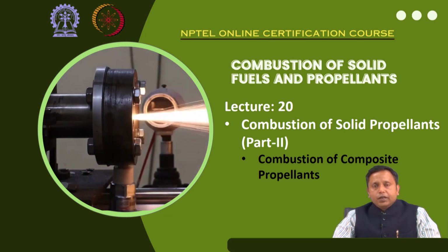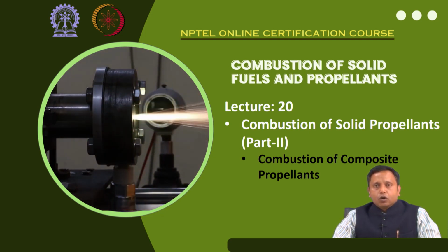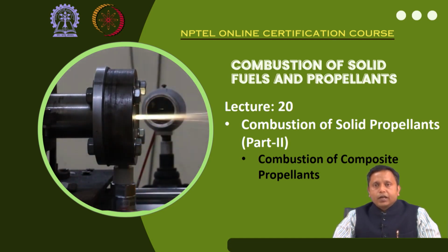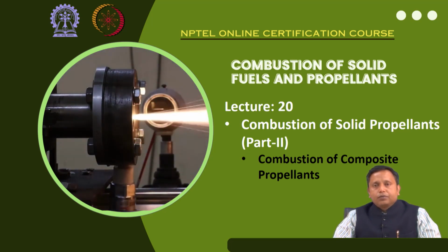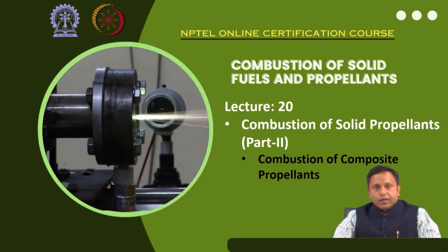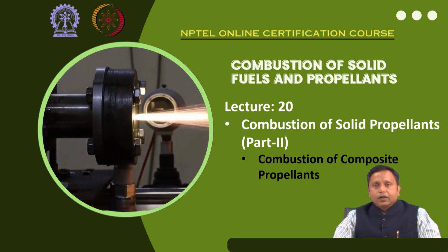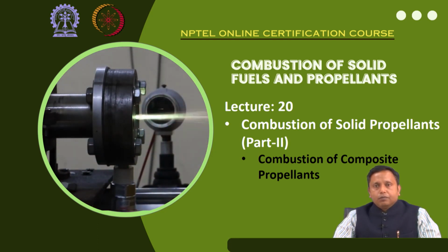So, we will mostly emphasize the combustion of composite propellants containing ammonium perchlorate as the oxidizer, and HTPB, which is another workhorse binder for composite propellant. So, we will consider the combination of ammonium perchlorate as oxidizer and HTPB as the binder or fuel for solid propellant ingredients. And there we see how the decomposition of ammonium perchlorate produces a certain flame, which is going to further react with the fuel species, and that will help in burning the fuel species present there, and how the structure of the flames are coming.